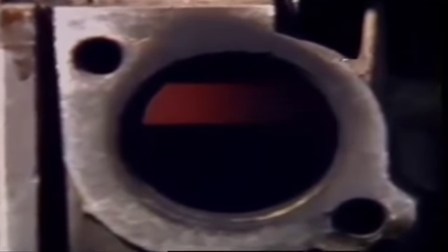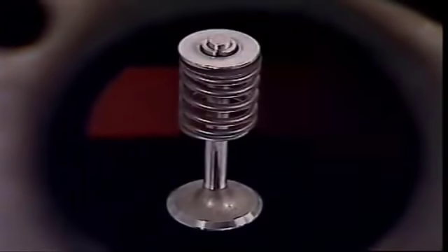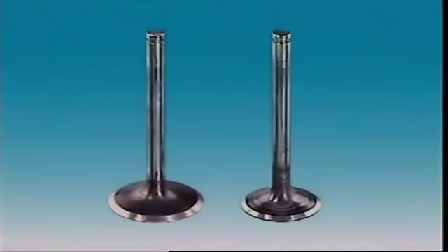Exhaust valves withstand huge temperatures, and they can become red hot. A valve must not soften at high temperatures. It needs good hot strength to stand up to being forced against the seat and to prevent tensile failure in the stem. It needs good fatigue properties to overcome cracking.